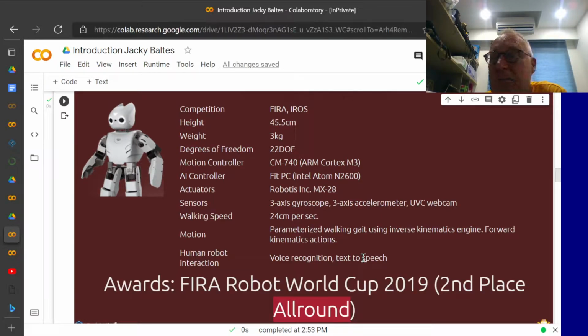So we have machine vision systems, for example, at various airplane manufacturers, Boeing, Airbus. You can put a workpiece in front of the vision system, and the vision system can tell you that this particular rivet hole is off by 1 millimeter, or it's not quite round enough, it's more egg-shaped. That's something over hundreds of thousands of different rivet holes in order to build a plane. That's something that humans can't do. If you're looking for exactly this kind of hole on exactly this kind of workpiece, a machine vision system can do a phenomenal job.